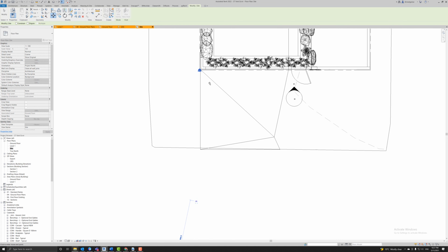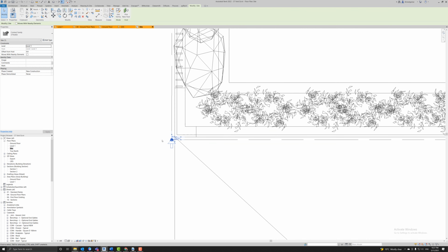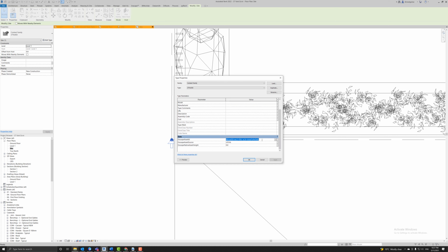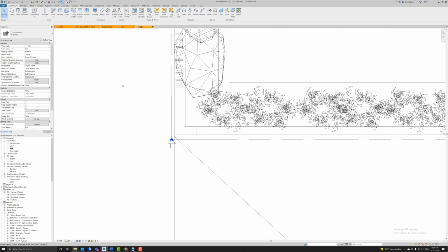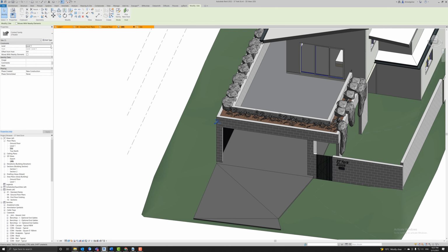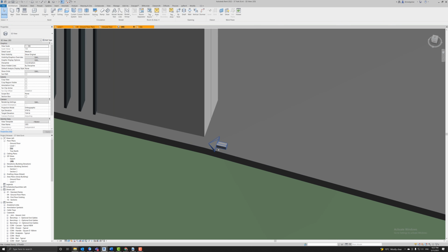I'm going to pick that, and you can see because the origin in Blender was all based around that point, if I bring the context in that location, it should be there too. I'm just going to clear out this Enscape asset ID so it's blank for this particular type. I've also got it at the wrong height, so I'll just put it at ground level, but you can see a little arrow there.